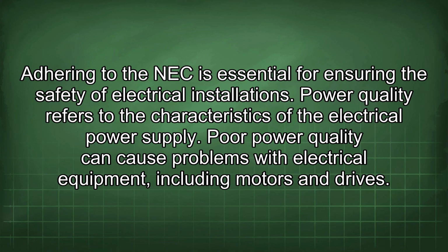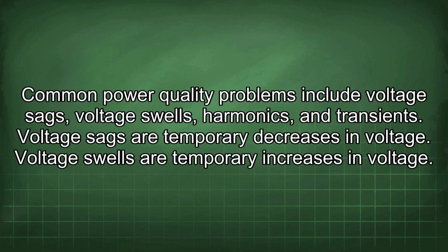Power quality refers to the characteristics of the electrical power supply. Poor power quality can cause problems with electrical equipment, including motors and drives. Common power quality problems include voltage sags, voltage swells, harmonics, and transients.